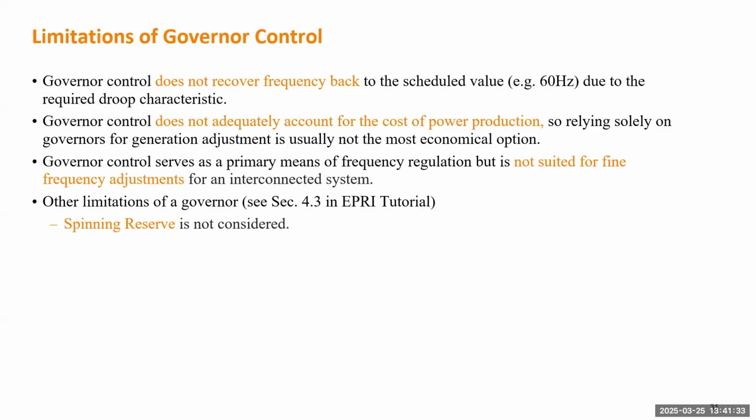That's why it's called spinning reserve. There's another type of reserve, which is non-spinning reserve. Non-spinning reserve means the unit is not spinning, but if you need it, it can be started quickly to become reserve. For instance, you have another